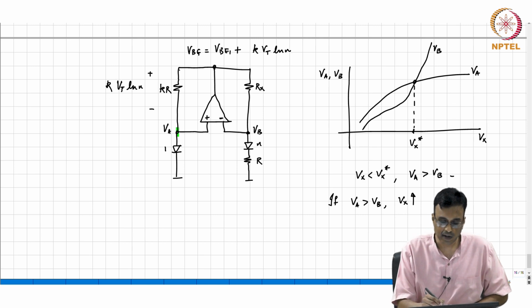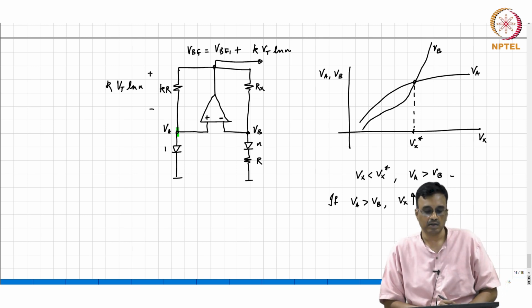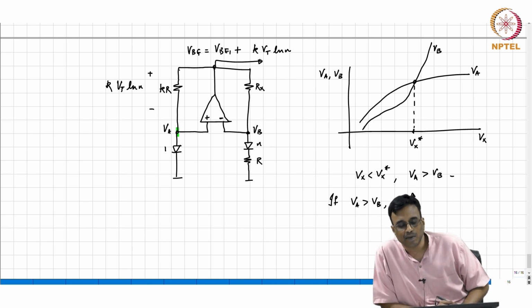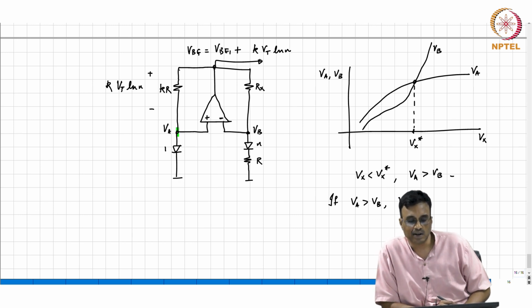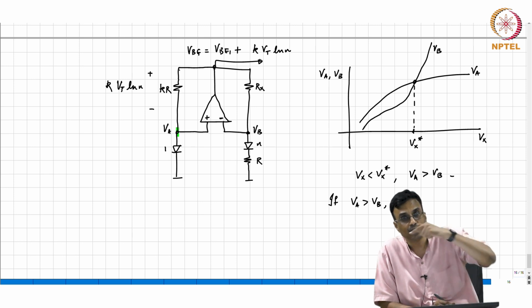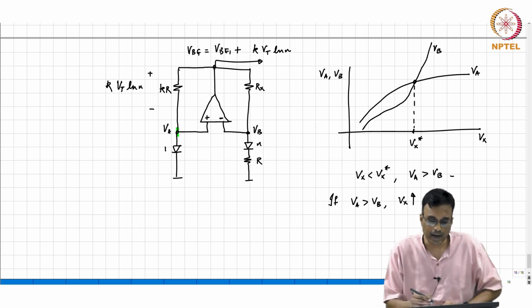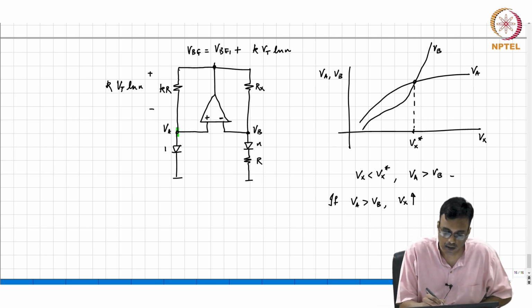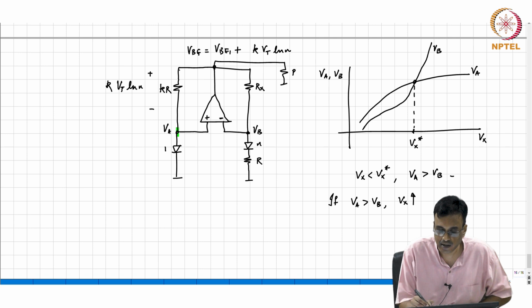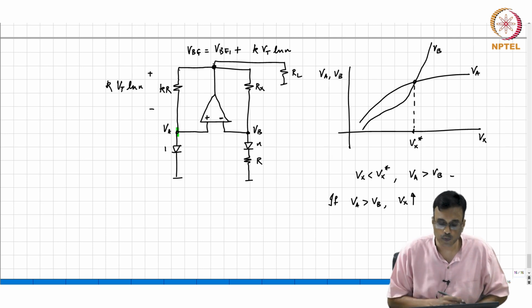And the advantage of this is, what might be the advantage of this? Well, there's a very small thing, right? Now you have 2 extra transistors, but in the op amp you have like 500 million of them, so it really doesn't matter. All right. The nice thing here is that you're taking the output of the op amp. So if you connect a load here, if you put RL here, what comment can you make about the output voltage? Will it change?